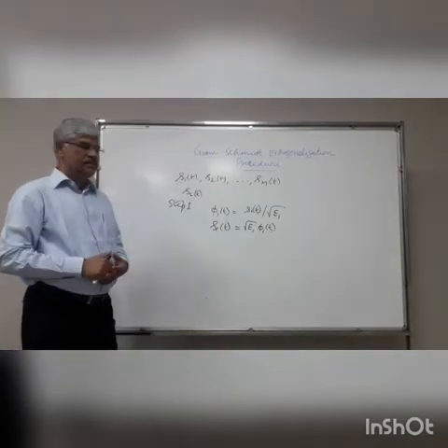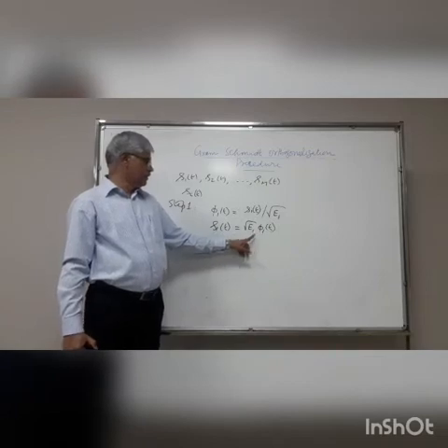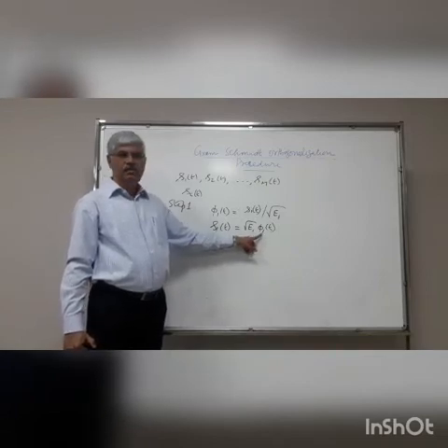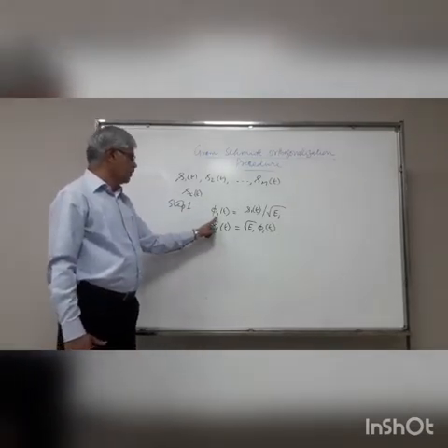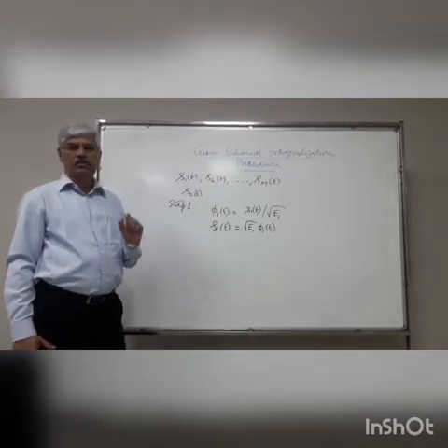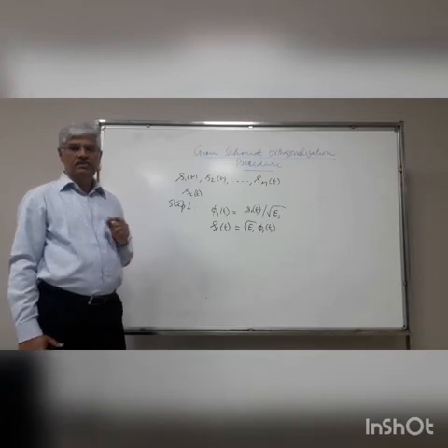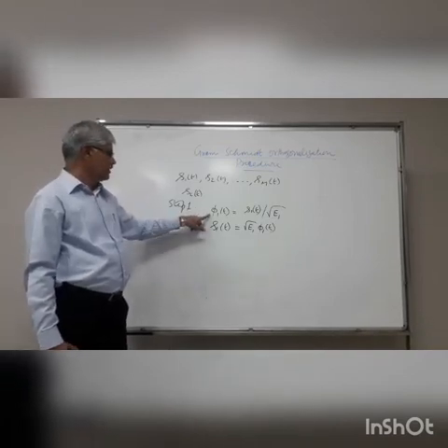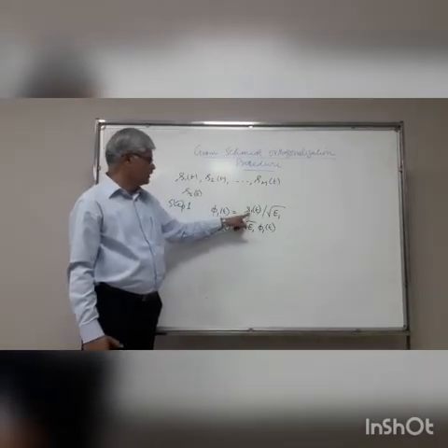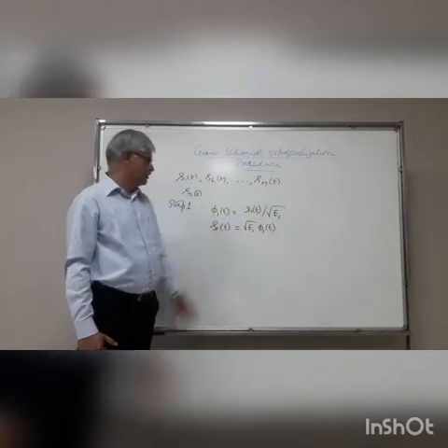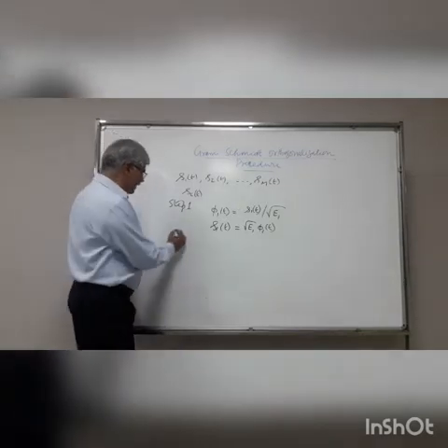This tells us that phi 1 of t is a unit energy signal, whose amplitude is root E1, and this is an energy signal whose amplitude is 1. So energy is 1. So this is one waveform of a set of orthonormal functions that has been obtained like this. We define it from S1. S1 is known to us. We can always find the energy of that signal and represent it like this.